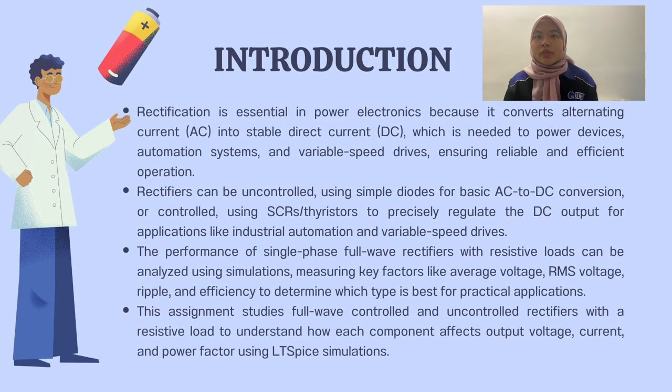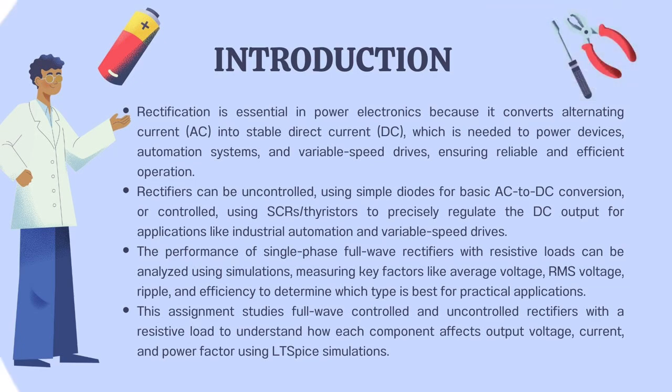The performance of single-phase full-wave rectifiers with resistive loads can be analyzed using simulations, measuring key factors like average voltage, RMS voltage, ripple, and efficiency to determine which type is the best for practical applications. This assignment studies full-wave controlled and uncontrolled rectifiers with a resistive load to understand how each component affects output voltage, current, and power factor using LT-SPICE simulations.